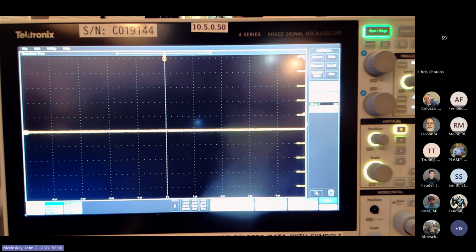You can set a constant signal generator level and sweep across the frequency range to get an approximately constant short circuit current. Okay. I can go back and show those charts here just to review that theory. Well, let me do that now, because I want to make sure we understand that.